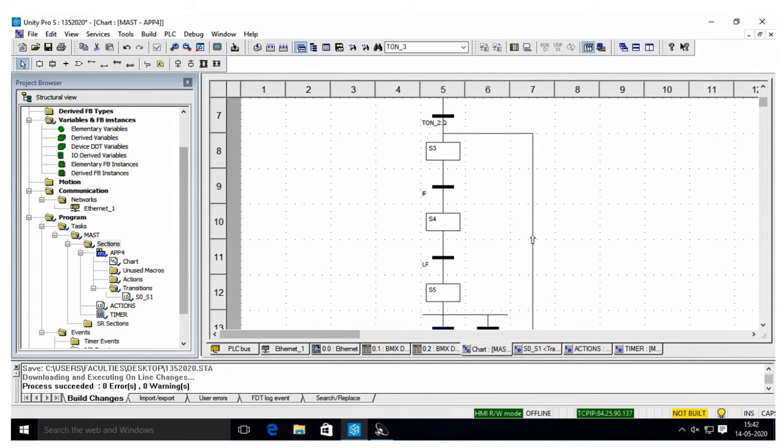The S3 step, it will check for the condition. Okay, how will the condition be checked? So here S3 condition, what is the action plan? The S3 condition, the drill motor will be on, and once again the cylinder will start to return. It will come to the intermediate position. In the intermediate position only, actually the comparison or counting should happen. How many cycles completed or not.